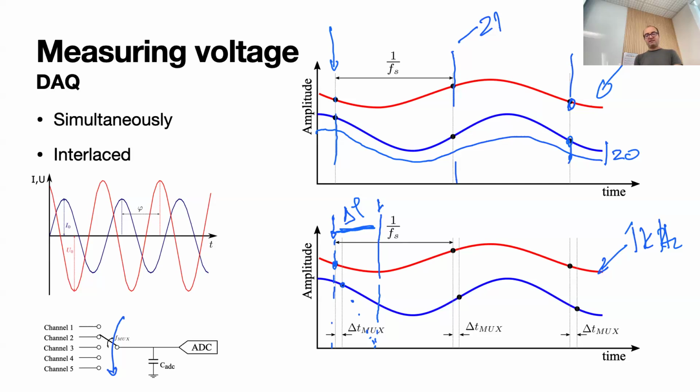We were using interlaced data acquisition, and above 1 kilohertz a phase error occurred that wasn't the consequence of the fuel cell, but a consequence of our measuring loop. Because this is a non-linear transformation, the Kramers-Kronig test failed. We were a little bit stingy, and for an experiment we bought cheap data acquisition, and we paid a price: now we have limited EIS. But at least it's good teaching material, if nothing else.